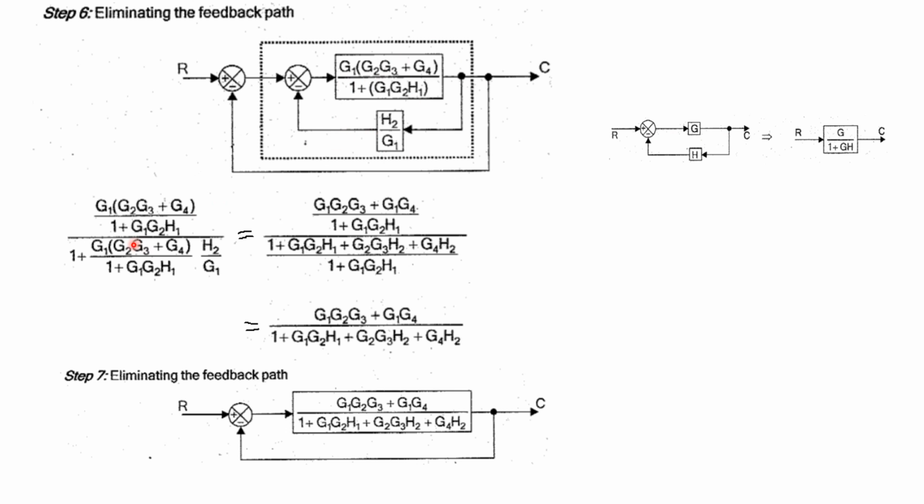When we are applying the formula for negative feedback, it will be a big expression. That is, this and feed forward gain, this and feed forward gain divided by 1 plus, because here we have a minus sign, so here you have to put plus. Okay, feed forward gain into this feedback gain, H2 by G3.